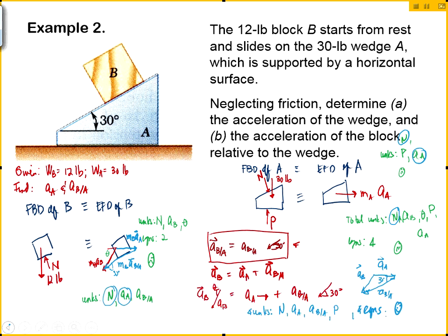From the FBD of B, what are the 2 equations I can set up? I'm not even going to try rotation, because along any direction I will have at least 2 unknowns. You agree? You usually do perpendicular and parallel to N when you want to avoid an unknown, but if you go parallel to the incline, this one will still enter anyway.